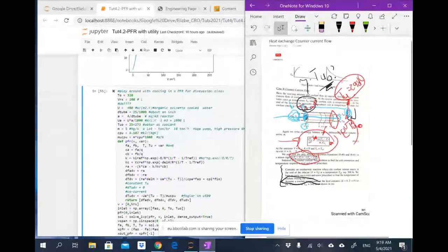So this is the start of my integration boundaries. And we are going to ask for the code to constantly give us the outlet value there. And we are correct with our guess value as soon as this outlet temperature of my utility is what it actually is at the outlet. So what the temperature is that I've got the cooling water available.